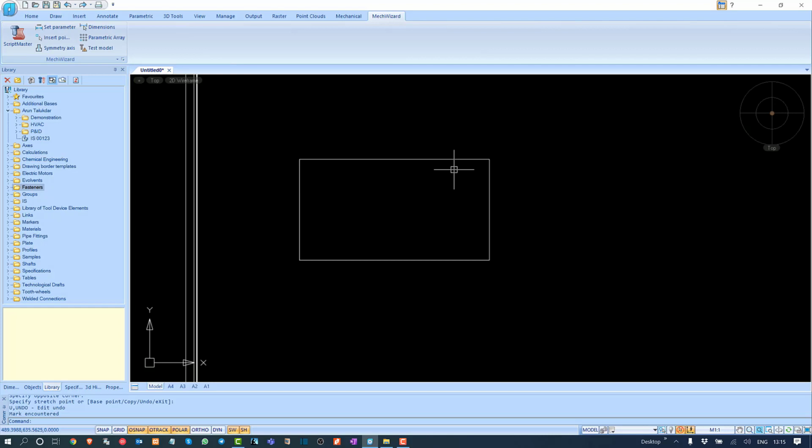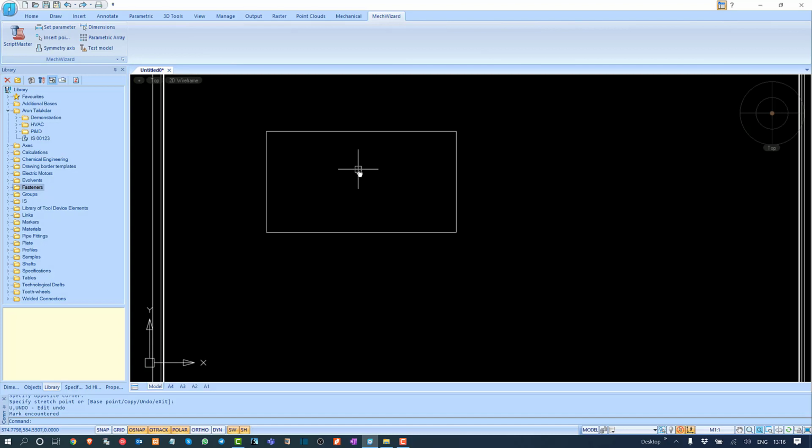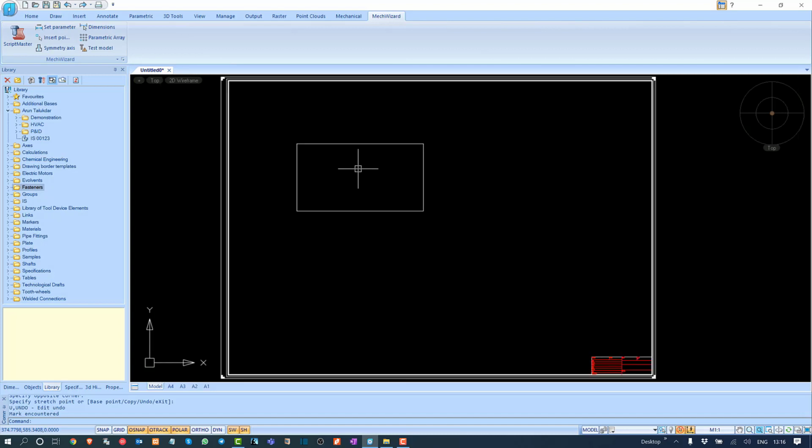And here, for this basic component, we can say that there will be two different variables. One is length and one is width. So these two variables will provide us the entire rectangle. So our intention will be to track the length and width instead of objects. So anytime we will use the dialog box to ask the value of the length and width from the user, that will be added in the backend of nanoCAD Mechanica to form the rectangle. So this is how it works, and let's see how we can do it in nanoCAD Mechanica.